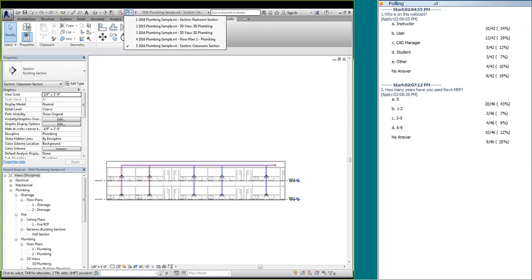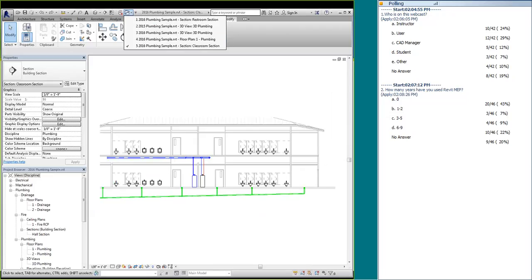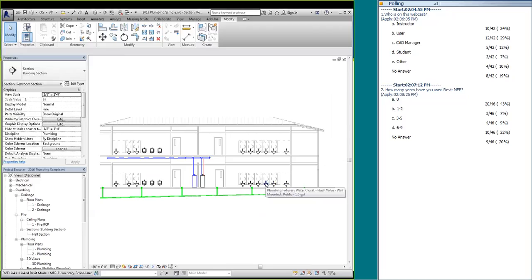And one other thing that we did, let me see if I have our drainage here. To teach the 3D restroom section, there it is. To teach the sloped piping, instead of doing the much more complex one when you have to do it with the toilets, what we did was you put in drains, and then the floor drains, and then you do your sloped piping with the floor drains. So again, the tool that you can do beyond that then is to go ahead, now that you've learned how to do the sanitary system here, and then apply it to the other ones that are available.